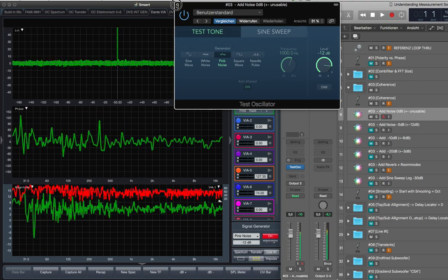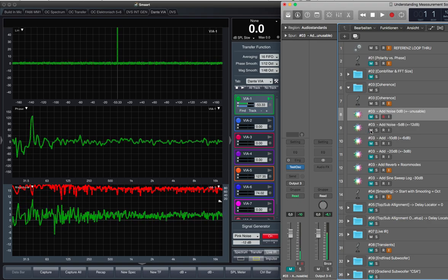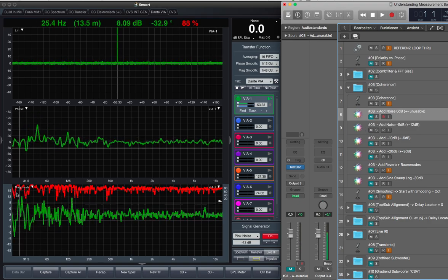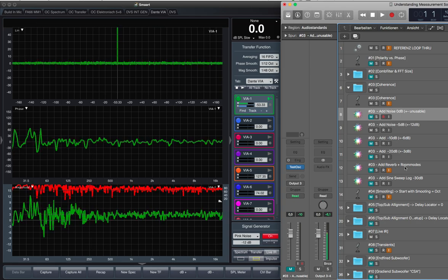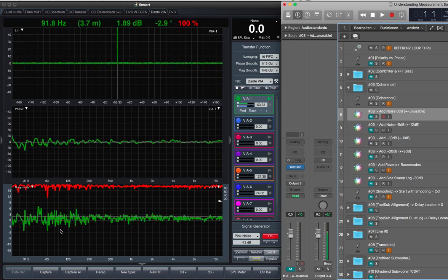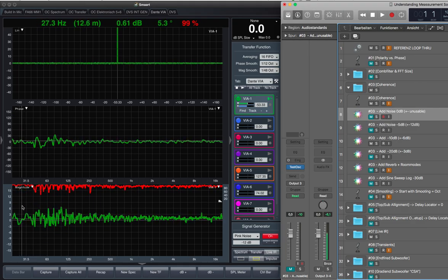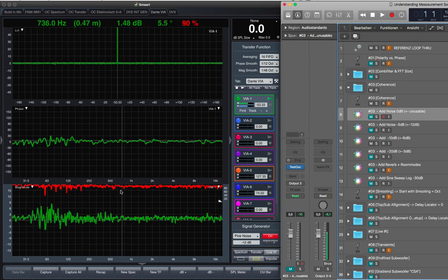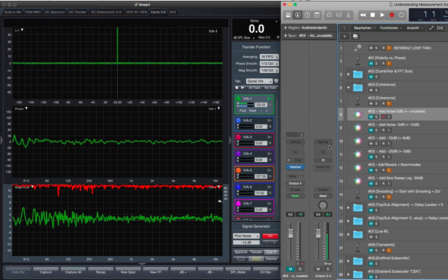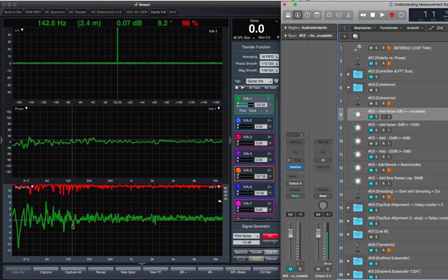And so let's mute this channel and add the noise with -5 dB. Then I have a ripple of ±12 dB. Same with -10 dB, and the ripple is gone to ±6 dB. That's a good real-life situation here for measurements. You should be able to measure your signal with such things.